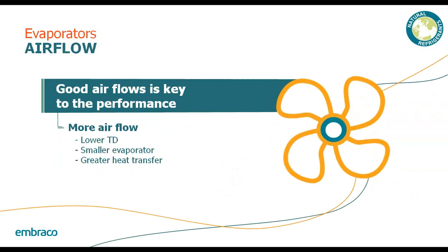One thing to consider is airflow is very critical to the behavior of your evaporator. You want to make sure you have as much air moving across the evaporator and that it's not spilling into other areas of the cabinet and bypassing your evaporator. If you have the capability, try and do some CFD modeling to ensure that the airflow is flowing in the correct direction, or try and use some tape to monitor how the air is flowing through the cabinet.